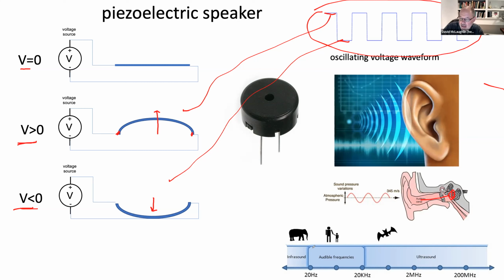And so we're able to hear things between about 20 hertz and 20 kilohertz. As you get older, this low end goes up and this high end goes down, and that's a combination of listening to loud rock music and aging and other environmental effects. But you can use this little piezoelectric crystal, and we can create a square wave at a certain frequency. And because of everything we just talked about, the way it tickles your ear, as long as it's in this range, you'll hear it. You'll say, aha, I recognize that as 1 kilohertz. So let's do that now.